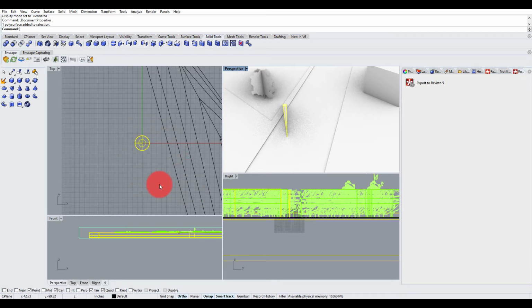But again, Revizto is positioning based. So in Rhino, if I know that I've drawn this, I can reference my XYZ values down here at the very bottom left, and I should be able to pretty clearly see, okay, I've dropped this sort of pin-like icon in the 0,0,0 positioning. And that'll make it really easy back in Revizto. If I do need to move things around or reference anything, it just gives me a point to measure to.